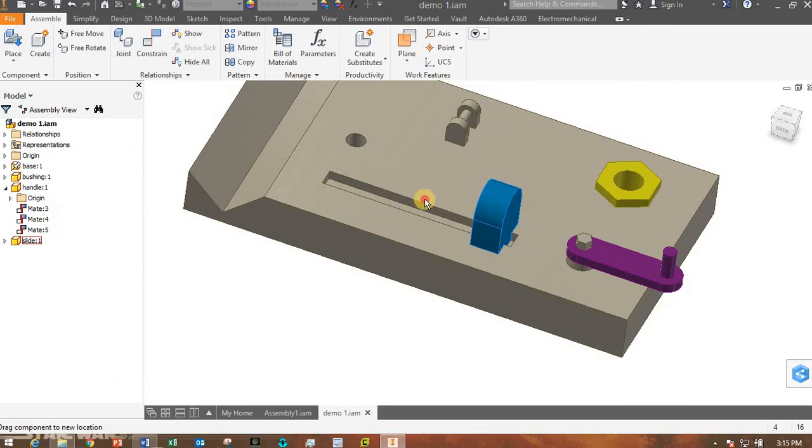We'll see what happens. Well, I can move this now a distance of 20, and then it stops. Okay, well, I need it to go further than that. Let's right click on this mate here, and now notice right here you see this plus or minus. This plus or minus says that there's a limit there. Okay, and these don't have a plus or minus because there's no limit.